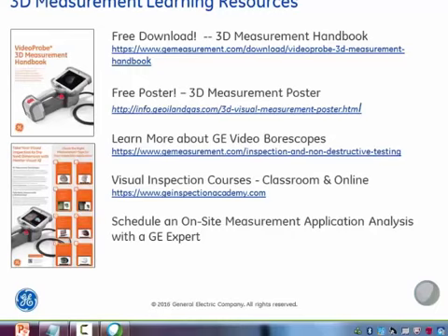Okay. Hey, if I can, this is Paul Thompson. There's one additional piece I'd like to add to it because your question is spot on. You just don't know when you're using some measurement types if you're in that sweet spot. And that's especially true for your traditional stereo, which is a 3D measuring system, but it's only at the point of reference where you're measuring. You don't get the point cloud. And so until you have that point cloud to look at the health of the information which you're actually using, you just won't know if you're getting good measurement data or not unless you do many measurements, take a lot of time, and look at the variation of how much of the measurement value is changing with each pixel measurement.